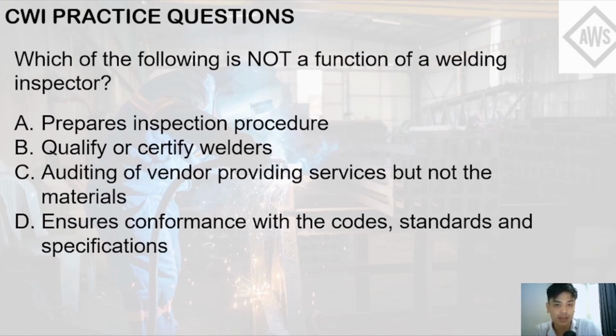Documents like MTRs, mill certificates, the factory standards used for the production of the base metal, and the destructive testing used prior to shipment should also be analyzed and scrutinized by the welding inspector.